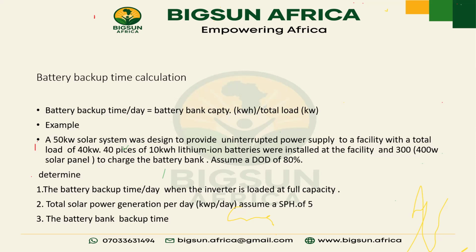What I mean by this is like this. In this my house, if I'm not at home, the only thing that is on in this house is my fridge, which is like 150, 170 watts, right? So if I'm designing my solar, I'm going to design it that, okay, this is the load that is going to run for 24 hours. You put it down.